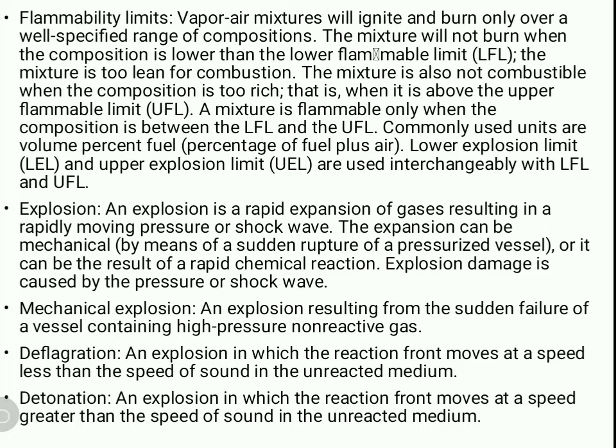So here the damages are very high. We have seen in the last videos that explosions may cause most of the damage to the plant. Then there are different types of explosion: mechanical explosion, dust explosion, and various other types. Now in a mechanical explosion, what happens? It is an explosion resulting from a sudden failure of a vessel containing high pressure non-reactive gases.